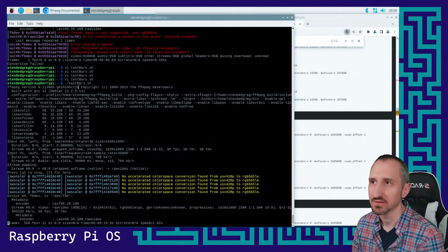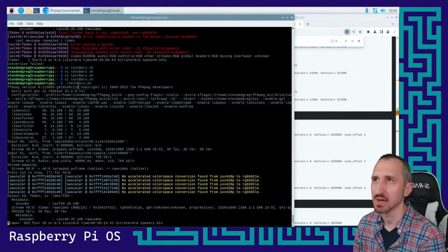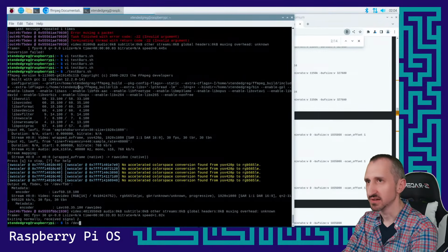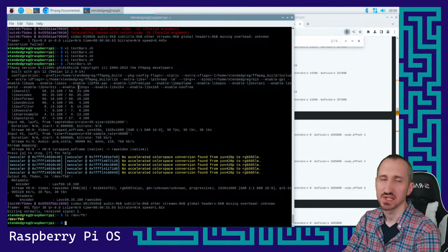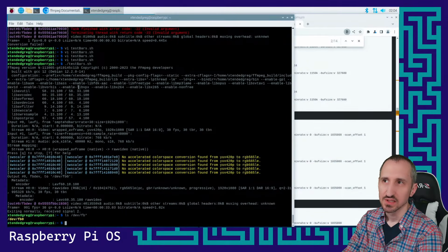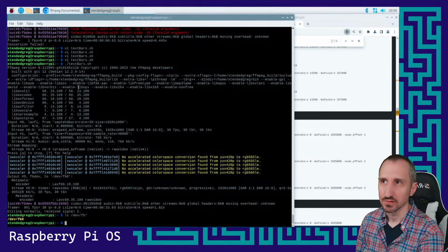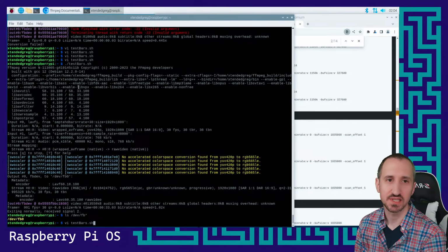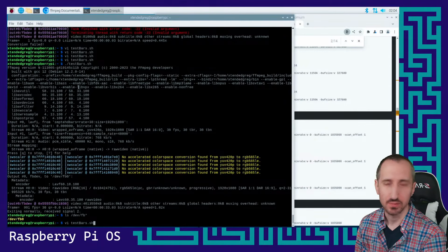It's usually very difficult to get full frame rate, but granted, we're not doing too much in terms of overlaying any text or anything else like that. But we do see that it is in fact running. Now, ideally, I would like to be able to see it. Let's see what we're actually currently using. So let's just do ls /dev/fb*, and we do see fb0 is our option, but I will say this, our operating system is actually overwriting it. So as it's pushing it to the screen, the operating system is going ahead and overwriting it. Which is fine. If we were doing this on Alpine Linux, and we did the same exact thing, we would see it actually output to the screen because it wouldn't get overwritten.